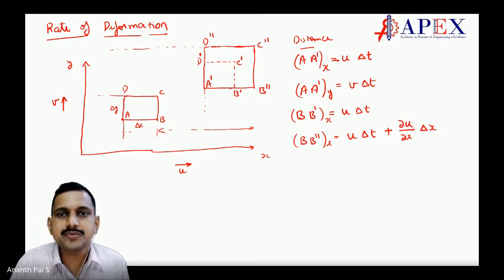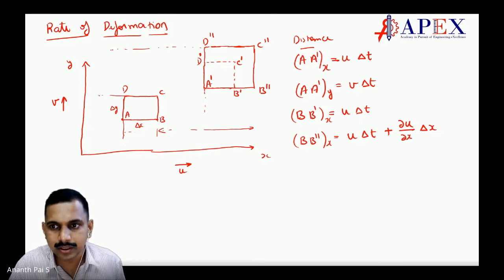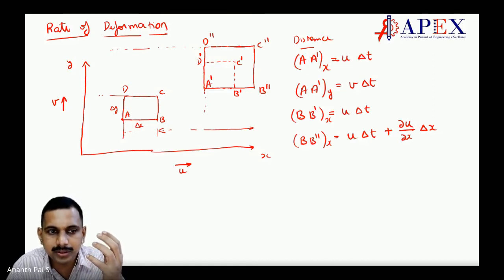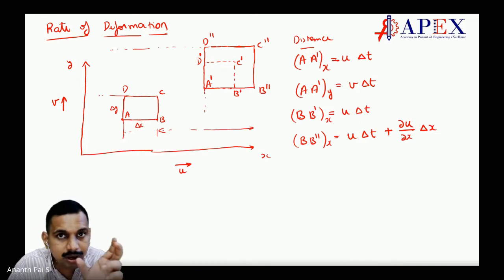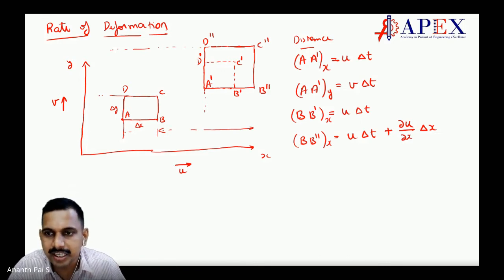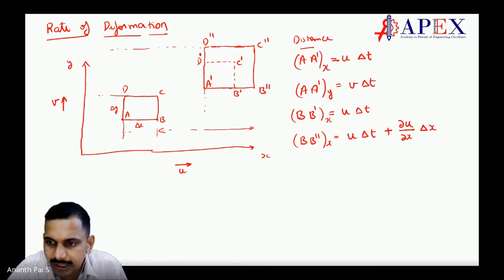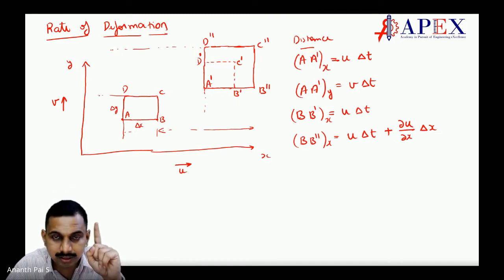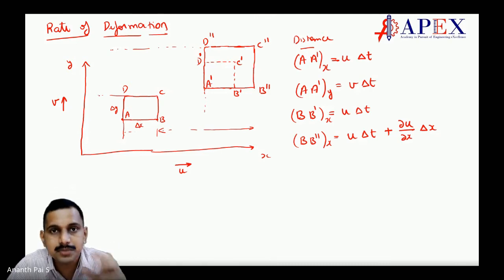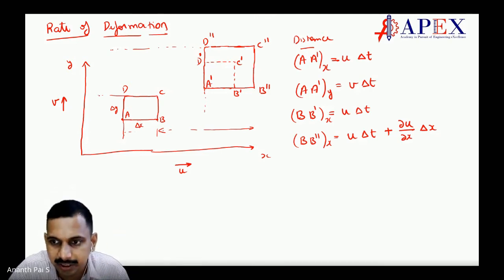This we do in CFD a lot of times, where we change the order of terms which we take into consideration, say like in finite difference methods or finite element methods. The order is important, or maybe finite volume methods. So order here means this order. This is taken as first order differentials, first order terms in the Taylor series expansion only have been taken into consideration.